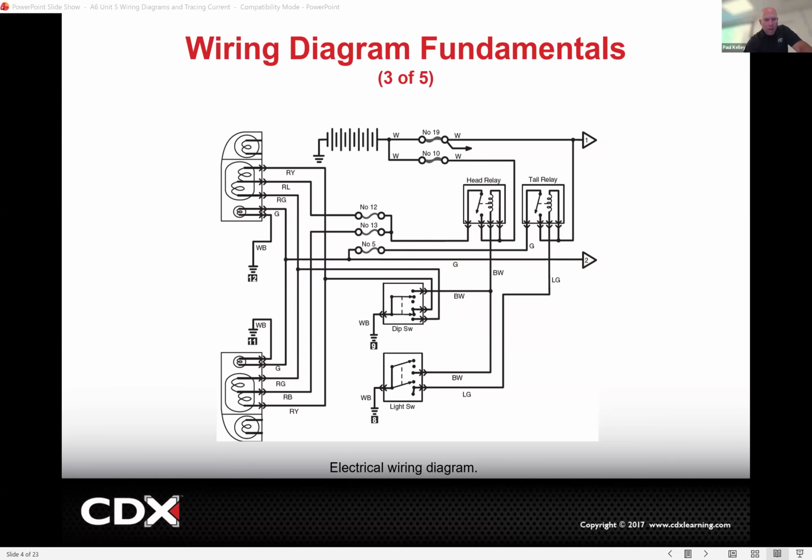If all those are out, do you think it's a problem right here? Because if the wire is broken right there, what would be affected? Just that one. But if I knew that 2 went out to the park lamps and those weren't working, I know the problem's not going to be back here.